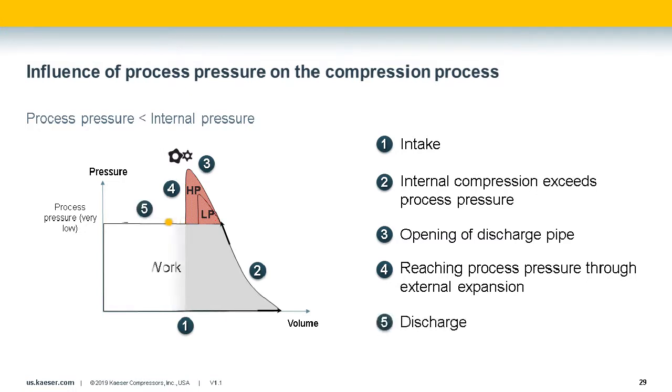So here we are seeing our graphic, and in a minute we'll see the overlay of the lobe blower. Here we can see the green part represents our savings by the curved line of the internal compression, and the red area represents our overcompression. So if our system pressure is less than the overcompression, we have to make sure that our savings justify it, which is why the new screw blowers have been optimized with their internal compression to minimize the overshoot.